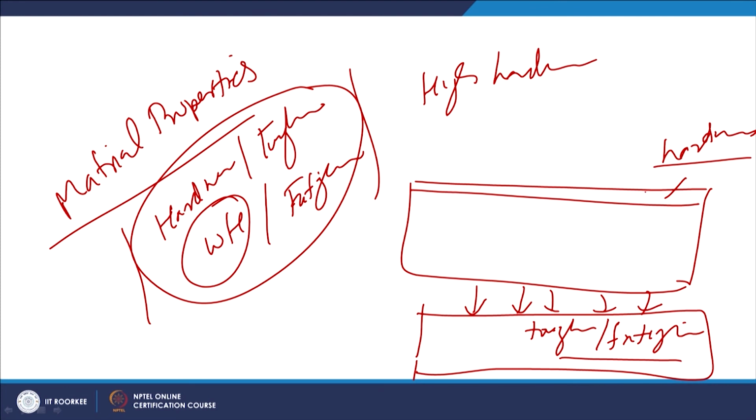Increase in hardness will reduce the depth of indentation and scratching, and thereby resist removal of the material in low angle impingement. So, surface hardening, carburizing, case hardening or development of hard surfaces through thermal spray coatings or weld surfacing can be useful for improving the erosive wear resistance of the material.